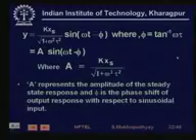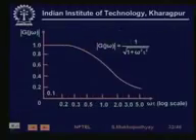So this is a mathematical solution. For example, the gain over different values of frequency varies like this. If the frequency is too low, then the gain is 1, because you are giving a slow sinusoid, which means that the instrument can always come to steady state and get the value of the input.